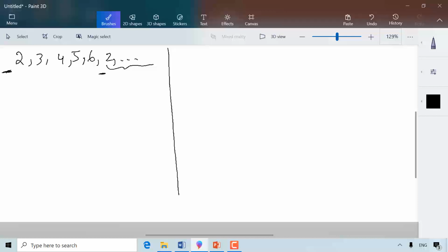Now, how many flip-flops do I need? Well, let's see. How many counting patterns do I have? 1, 2, 3, 4, 5. Five. Log base 2 of 5, ceiling. That means I need three flip-flops. Let's assume they are Q2 as always, Q1 and Q0.